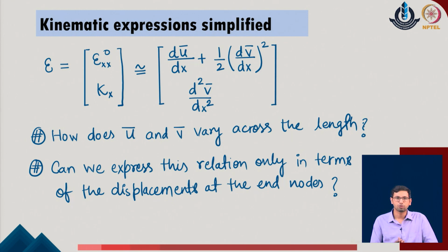But what is defined over here is a continuous expression of the displacement, which means that if I have this as a member which is having 2 nodes, I can know the displacement variation with respect to the given point from one end to the second end based upon a continuous function using these expressions, but I do not know the variation of the displacement at any intermediate point of the given system if I know the displacements at the ends of the given problem only.